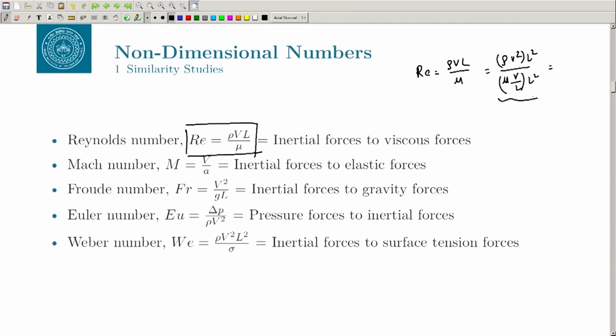If you know the boundary layer, and you want to find out what drag you experience, the skin friction drag or the viscous drag, you can find the shear stress, which is tau w, which is basically mu del u by del y at y equal to 0.